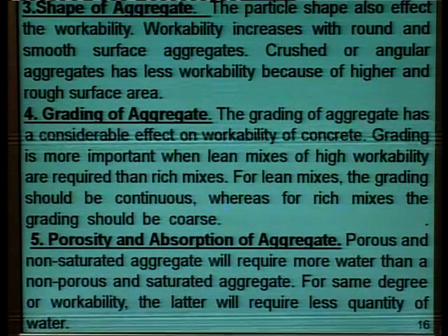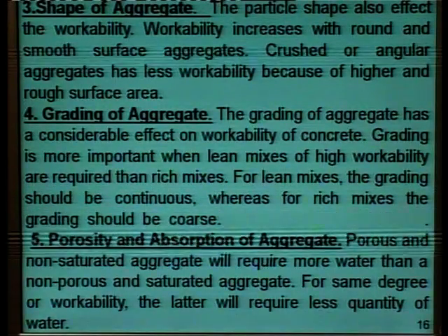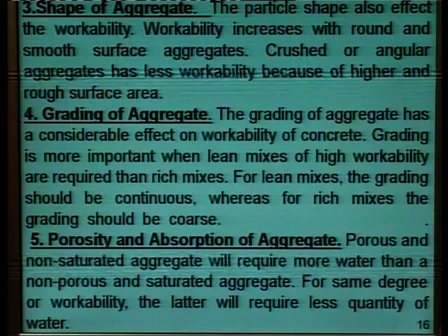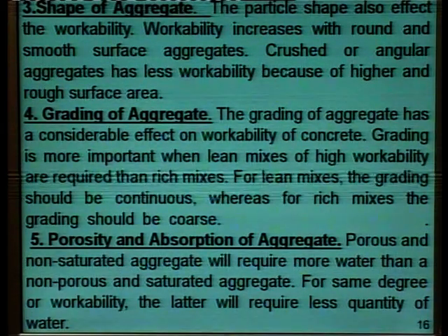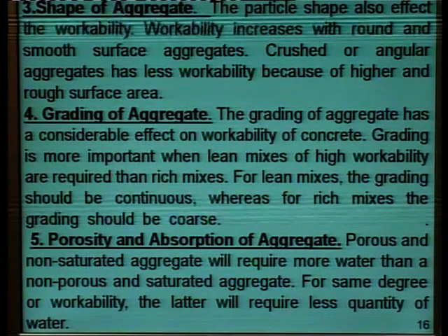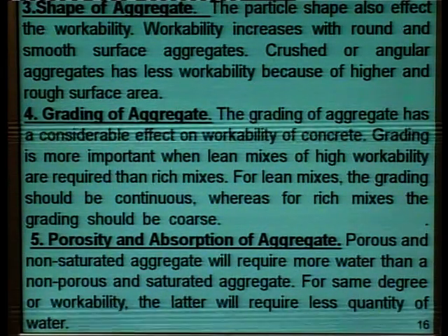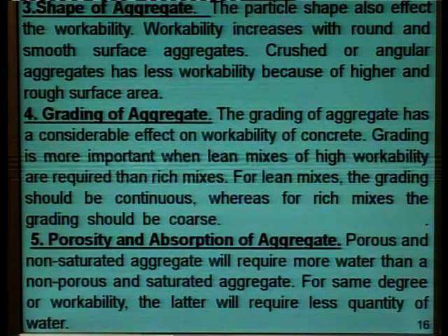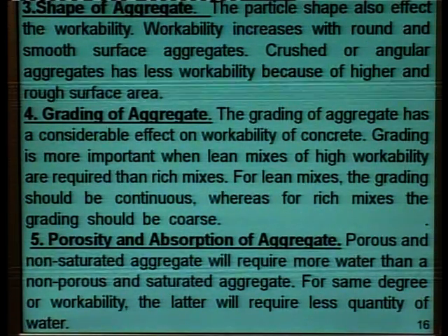Third is shape of aggregates. The particle shape also affects the workability. Workability increases with round and smooth surface aggregates. Crushed and angular aggregates have less workability because of higher and rough surface areas.